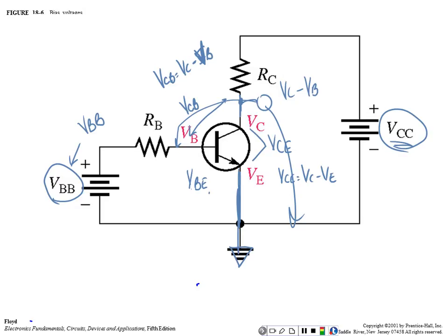So when we give you the leads, they're telling you what measurements to subtract from each other to come up with these things, right? Here VE is smaller than VC. So VE will always be smaller than VC, the forward bias thing, right? You understand? Because as long as we're not saturated. So what we're doing is we're taking the big minus a little. So your base is going to be about 7/10 of a volt greater than the emitter. Not exactly, but it's going to be that.